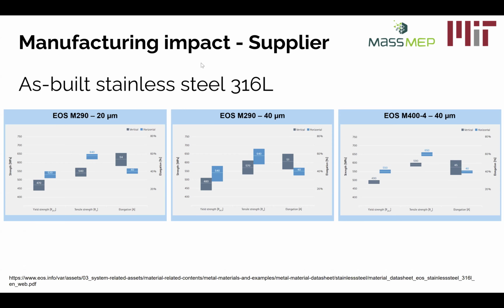And in here, they just measured the as-built conditions. Of course, it should be the situation. The numbers will be different again after heat treating, after doing all the subsequent post process. So it's something extremely important to consider when you evaluate which material you want to use. You need also to think how you're going to process this, with which parameters you're going to print it, and how you're going to handle the entire manufacturing chain.